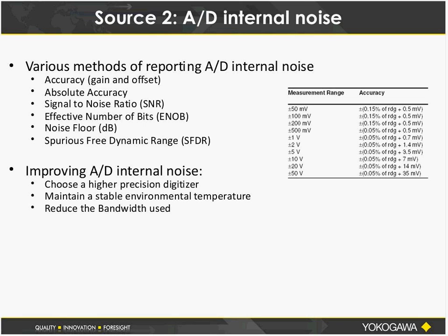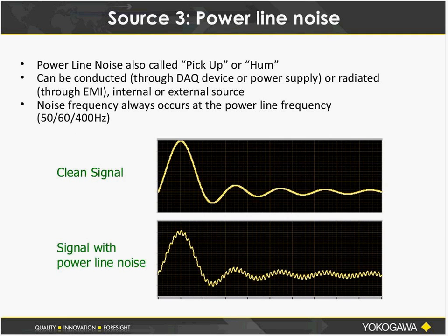So if you are in the market for a data acquisition device and you are concerned about measurement accuracy, I do encourage you to do side-by-side comparisons on the actual signal using a calibrated reference, and to discover which one is going to, in fact, give you the best accuracy under your test conditions. So keep that in mind.